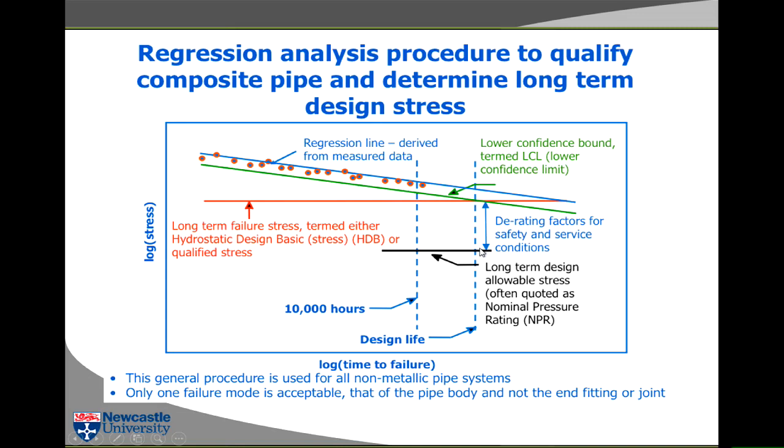And there are other various derating factors relating to safety. For instance, if you transport oil, then you'll have a different safety factor from the one that you have if you transport water. And if you transport gas, you'll have an even larger safety factor. So we don't need to go into that. We just need to talk at the moment about the hydrostatic design basis.